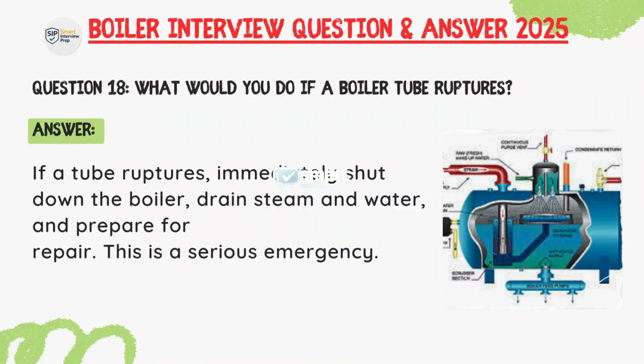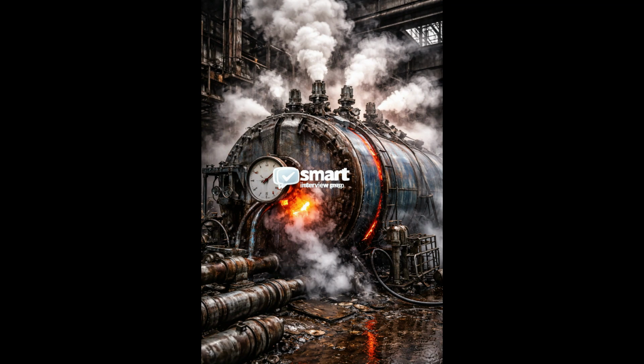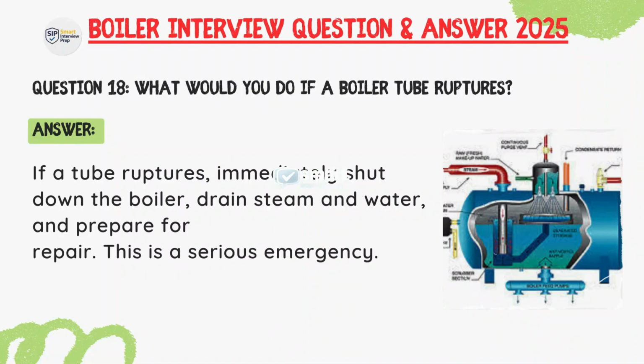What would you do if a boiler tube ruptures? Answer: If a tube ruptures, immediately shut down the boiler, drain steam and water, and prepare for repair. This is a serious emergency.